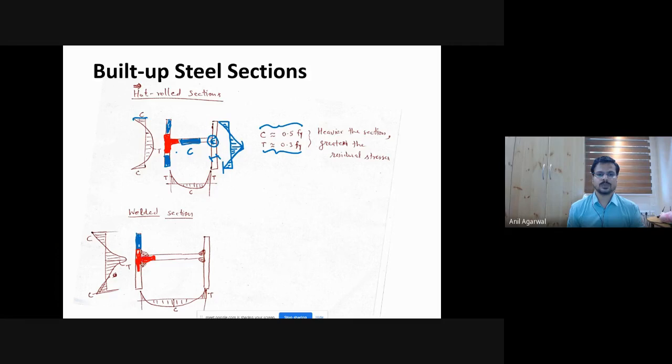Okay, but it will become hot at the same time. It will plasticize while it is becoming hot, because you have to clamp it to make sure that it does not distort. Okay, so it has plasticized, and now the two are of equal length, but this portion is hot, but the two are of equal length because initially it plasticized. Now when it wants to cool down, what will happen? Again, it will want to shrink, and this won't let it shrink. And as a result, you will have stresses developing like this.